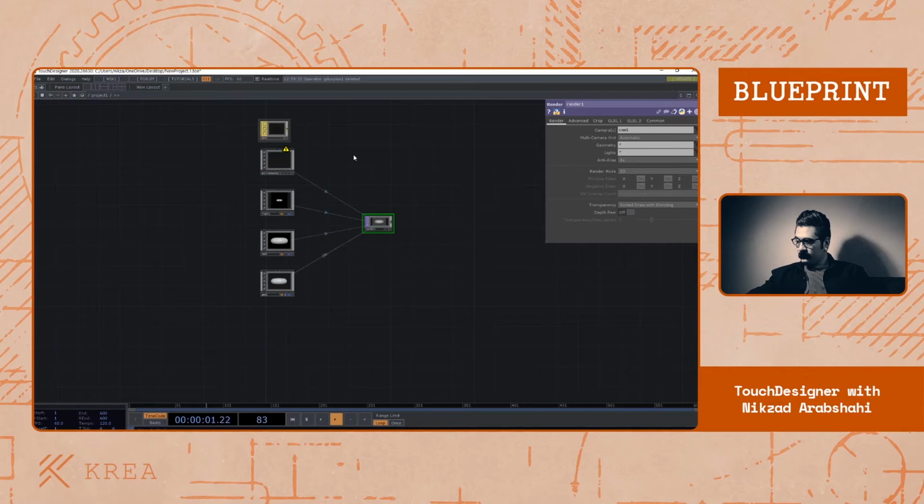So I strongly suggest starting a study on the PBR pipeline if you've never used it. Having a better understanding of how the PBR pipeline works helps you a lot to control all the reflections in your scene, or control the light diffusion, or make a more accurate, transparent or translucent material.